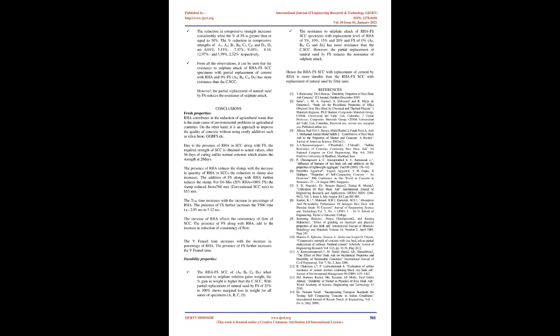The percent reduction in compressive strengths of A3, A4, B3, B4, C3, C4, and D3, D4 are 6.01%, 5.15%, 7.47%, 9.48%, 8.10%, 12.97%, and 1.99%, 2.52% respectively.